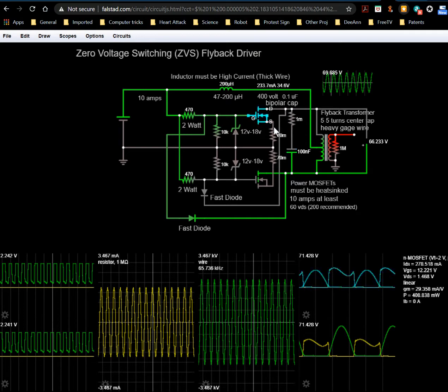It's basically got a glass oxide layer. It's vitrified. So this junction, these aren't electrically connected inside a FET. It's like a little plate of a capacitor, and yes, it has indeed capacitance across it. But at any rate, that affects it. But like I said, because of the presence of these diodes, this transistor cannot be on at the same time as this one. Again, if we remove those diodes, they could be totally independent.